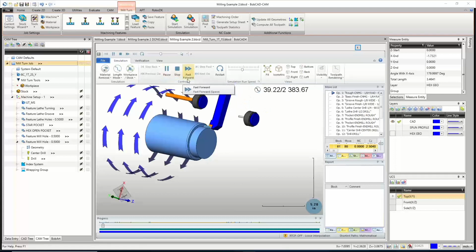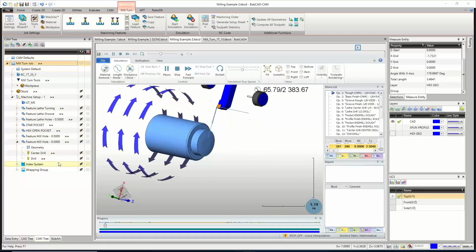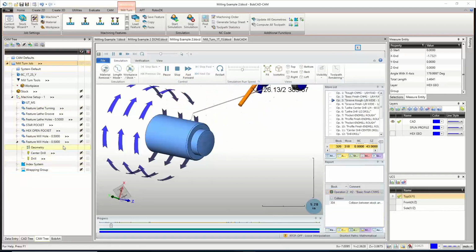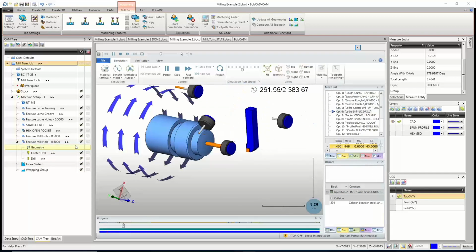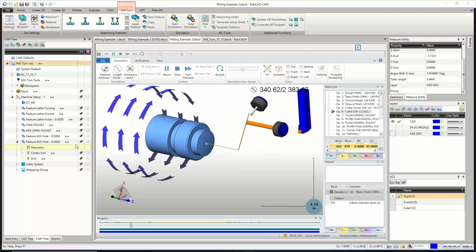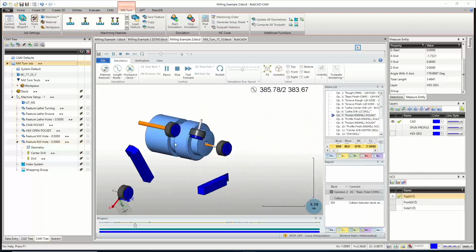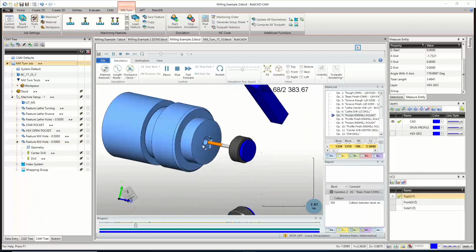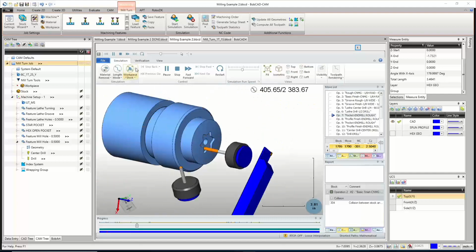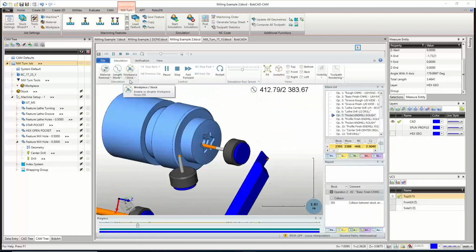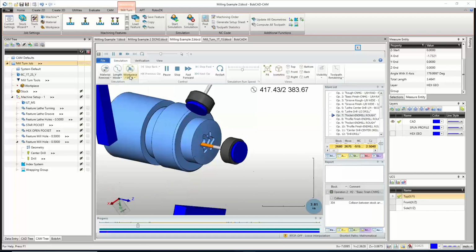Now, I did set it up so that the order in which I'm cutting my part should be the order in which it does this whole thing. So unless I made a major mistake, we should be fairly good. There we are, opening up that pocket. By the way, right now I'm on workpiece stock, so my part is sitting still and my tools are rotating around it.